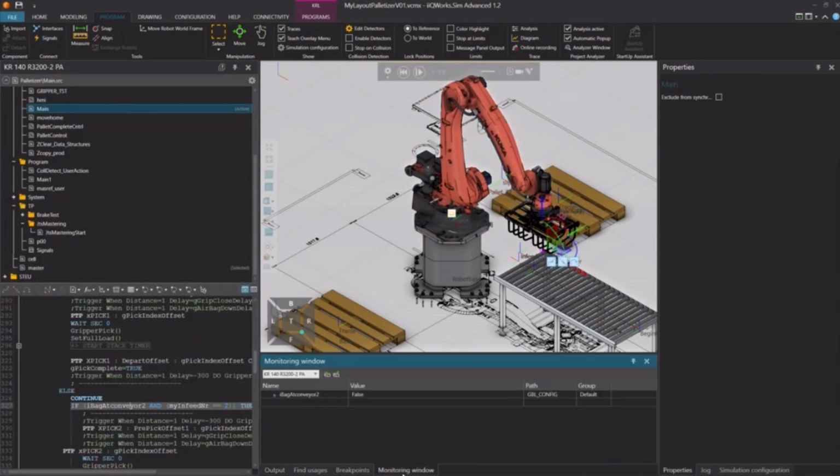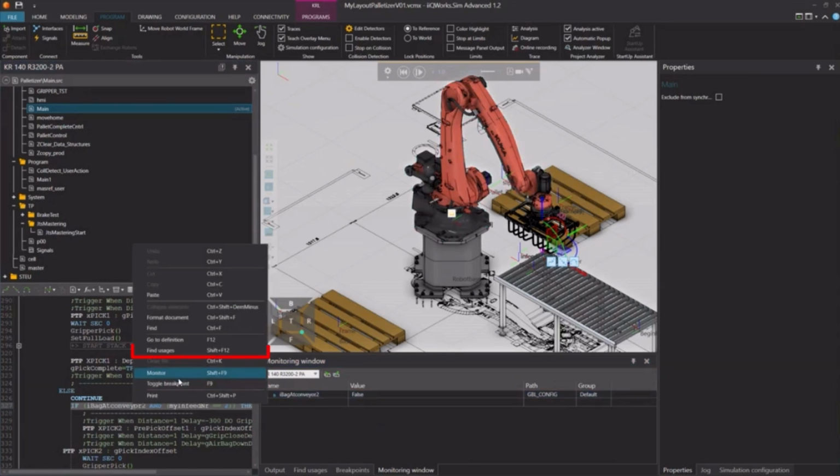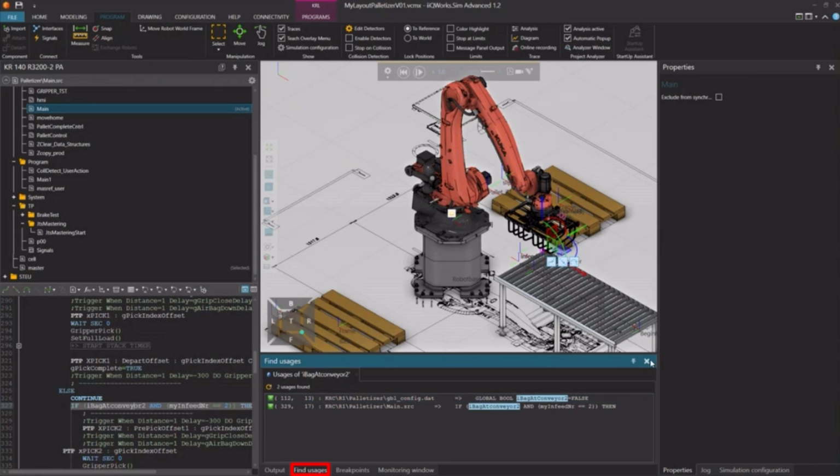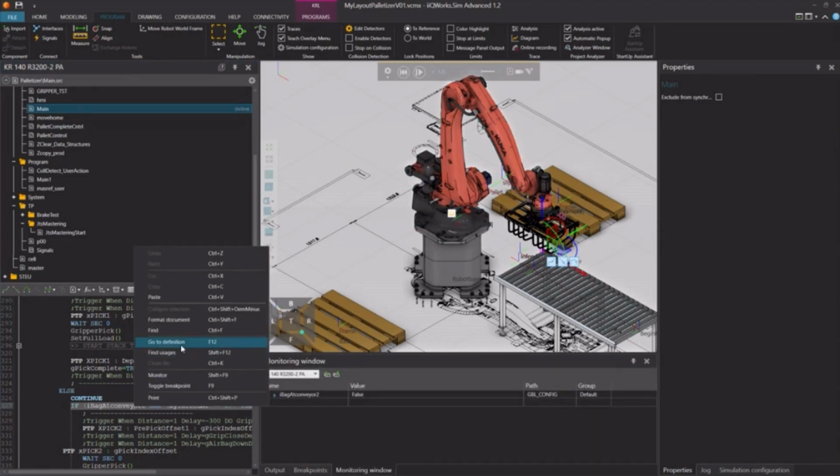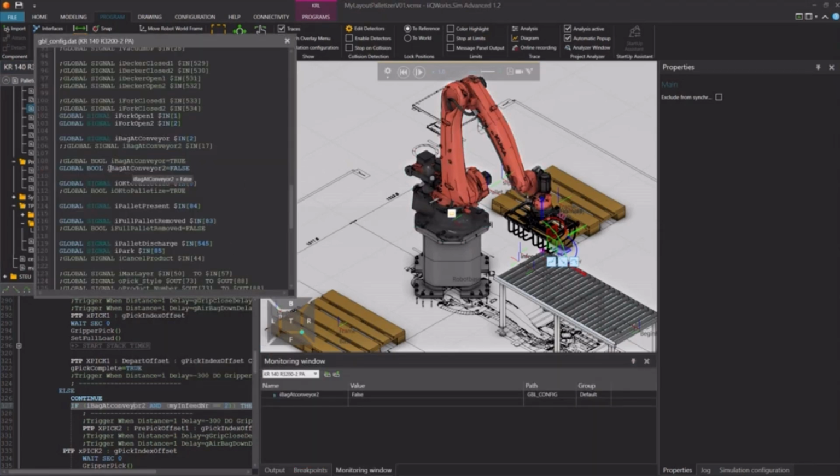The program stops because it is waiting for an input signal. The signal is monitored to identify why execution is paused. The input condition is temporarily bypassed by replacing it with a Boolean variable for simulation purposes. After resetting and restarting, the robot begins moving, confirming that the program logic is functioning.